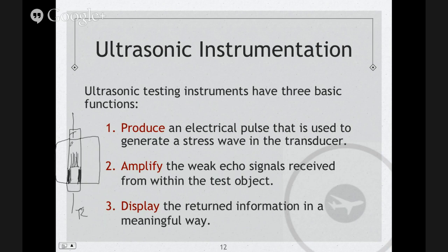And you also have to keep in mind all the attenuation factor by the material. Because of that, my signal over here is going to be very weak. So our machine also needs to amplify the weak echo signals received from within the test object.